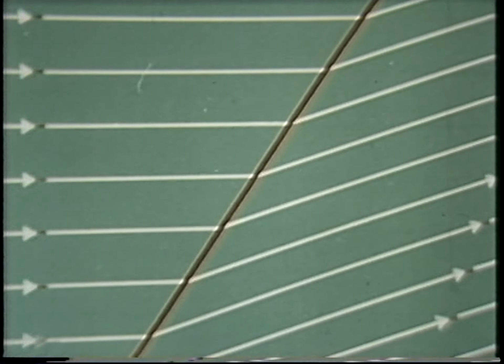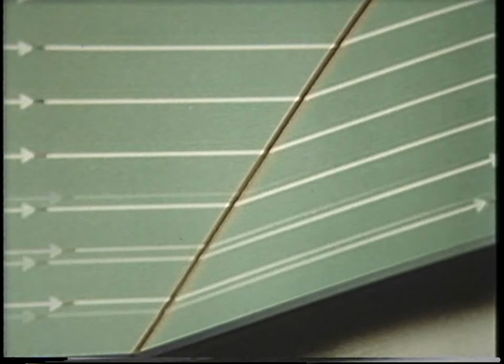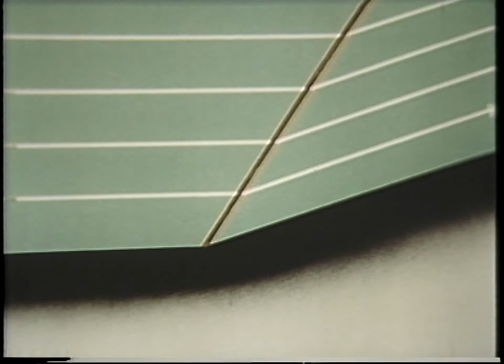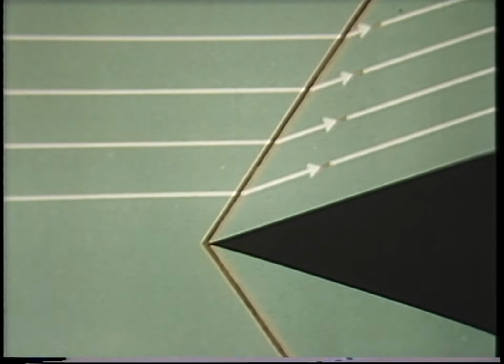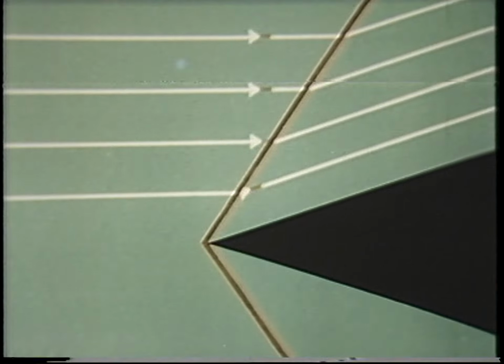A sloping shock wave, coming from the opposite kind of corner, swings supersonic airflow smoothly the other way. The corner may be at the leading edge of a wing. So supersonic aircraft can use sharp corners, as for instance, the double wedge wing section.